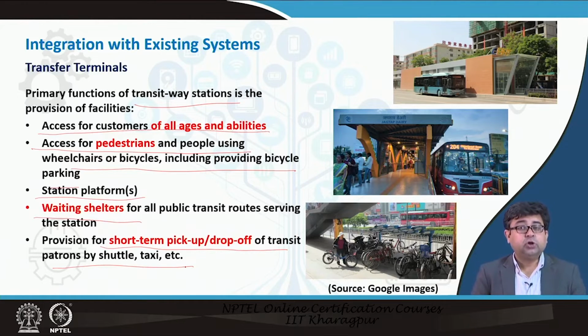Hence, you do not provide long-term or full-day parking for vehicles, but you should provide some minimum basic parking that will allow people to pick up and drop off passengers at those stations. Now, these may not be provided at all stations, but maybe at terminal stations or major stations where there is a lot of activity, a big residential complex or a big commercial complex.